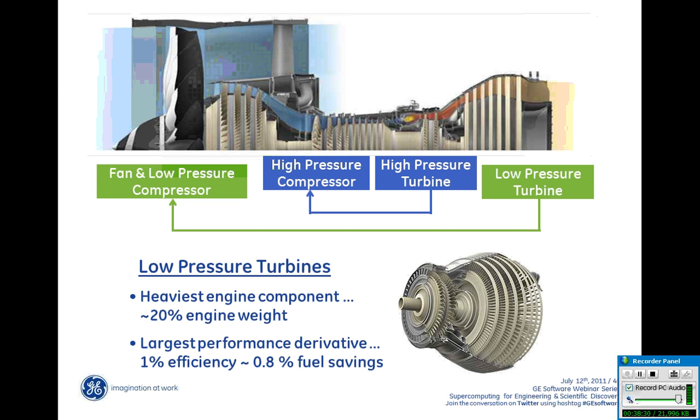So in order to do the simulation that you see described in the bottom right there, there's about 1,000 blades. Those are each of the spokes, and each blade is represented by 5 million geometric points with 9 degrees of freedom, so these are the variables, pressure, temperature, etc. We run 60,000 time steps for that, and that would be 2.7 petacalculations per case.